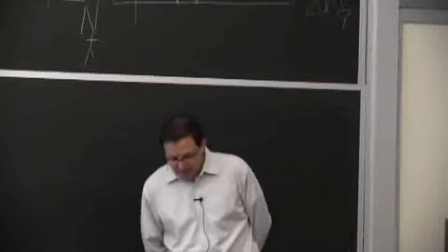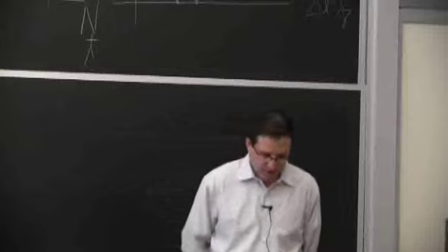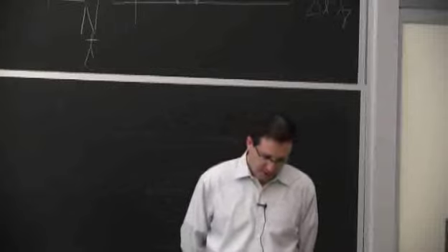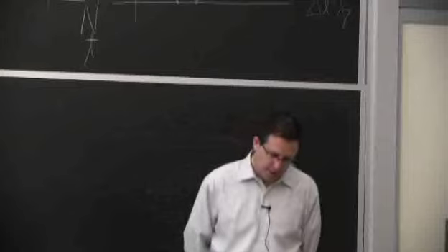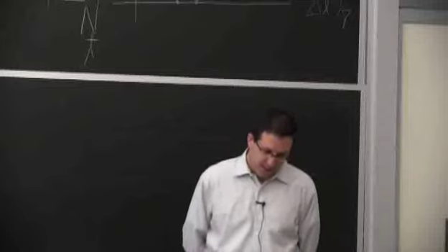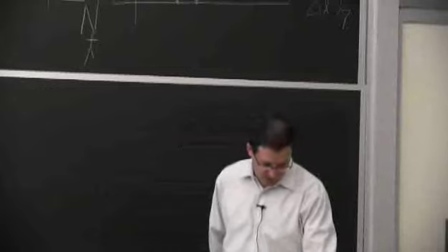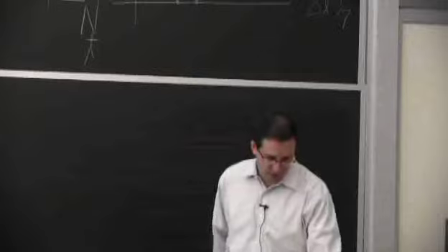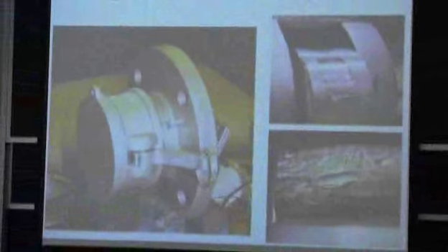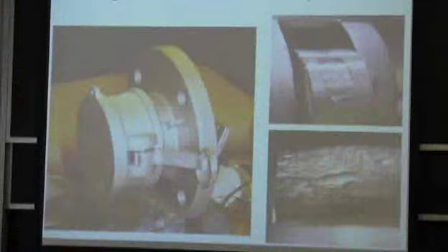Wear comes into play in processing for the tooling, and Professor Eager talked about lubrication and all of that. I decided to show you that example just to open your mind to the idea that if you're going to create this locking system for a cap on this flange here. So this is a flange to host a hose connector, and when there's no hose, then they put a safety cap on it, and the cap has this double cam shape here, so you see the groove. So you've got two chances of not becoming loose completely.